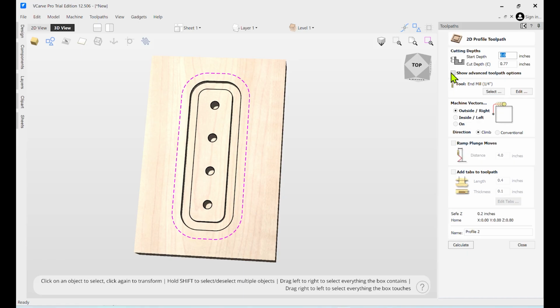What this will do is cut right through the material. Our material thickness is Z plus, let me do that again, Z plus 0.02. So our thickness plus 20 thousandths, that way it'll cut all the way through.